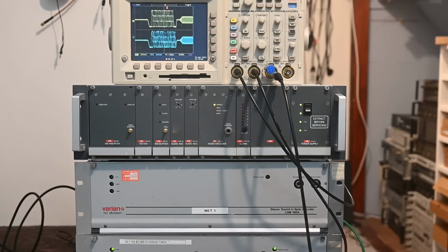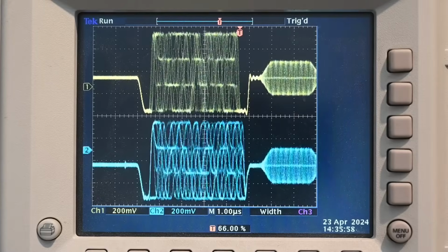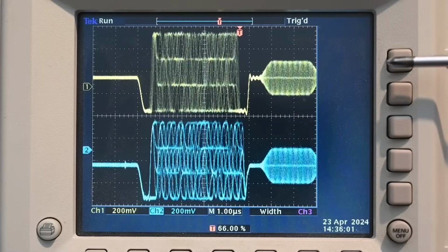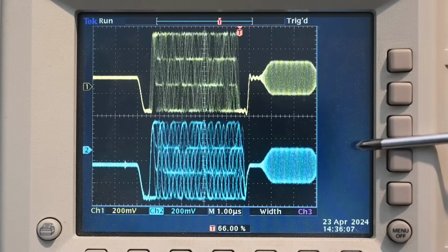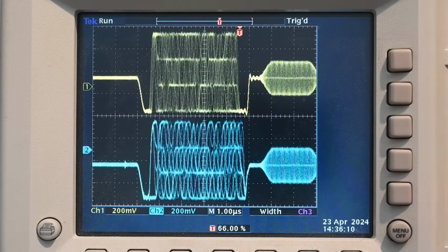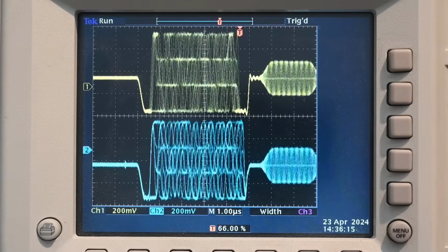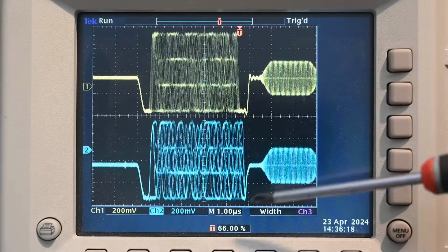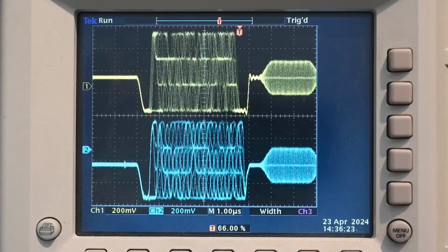They're both coding NICAM 728, they're both inserting it into the same horizontal sync period. They both even appear to be using the same coding scheme, so what's the problem? Why are they incompatible? What better place to start than the oscilloscope? Now, presently on screen we have the output of both coders here. The yellow one is the RE Technology IBA style coder, and the blue one is the TVT BBC style coder. Now, as I said before, while on paper they do code everything the same way, as in we have this quaternary encoding into the horizontal sync period, when we actually look at them like this, yeah, they do start looking rather different.